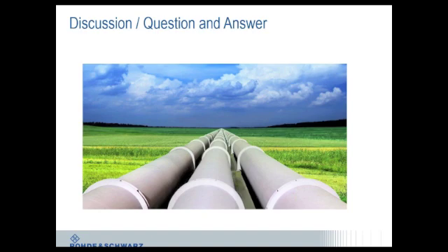Now, in the first case, if you're trying to test that a device can look at multiple carriers simultaneously, you obviously can look at the signaling messages to make sure it's actually doing that. The UE should have some kind of feedback or information that shows it's using multiple carriers. And ideally, if you're using multiple carriers, you should be getting a higher aggregated throughput than you would for a single carrier. The more difficult case, though, is how do you test the 2 component carriers at the same time?